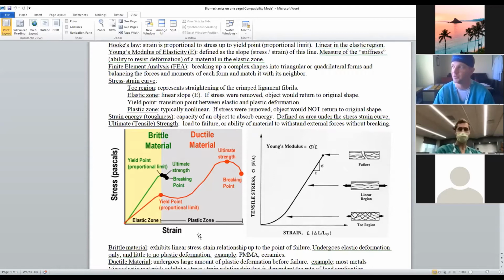So if you were in the lab doing an experiment, applying loads to tendons or applying loads to bones, you would actually be measuring a force versus deformation curve. And then engineers and scientists like to normalize things because depending on the size of the bone, if you're loading a femur or a phalanx, you can normalize them to their cross-sectional area. Stress is a more meaningful engineering term than force, because it takes a lot more force to deflect a femur than it does a phalanx, but their stress strain curves should be identical because they're both made out of cortical bone, right?